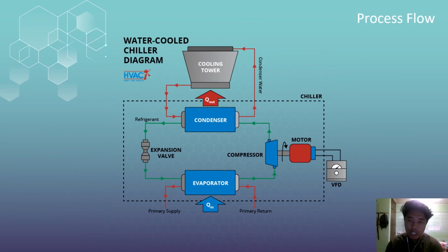through the condenser. In an open chiller, where the motor is separate from the compressor and connected by a shaft, the motor heat is rejected directly to the surrounding air. The evaporator load and the compressor work are rejected through the condenser, and the motor heat must be taken care of by the equipment room's air conditioning system.